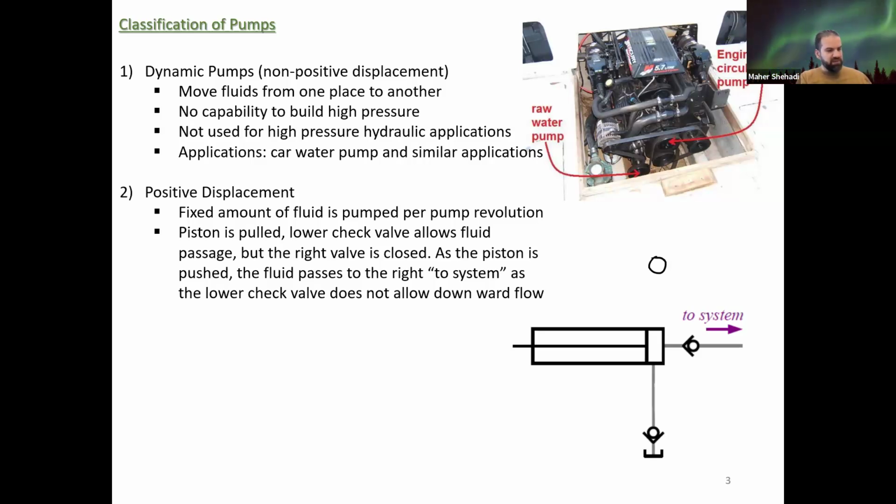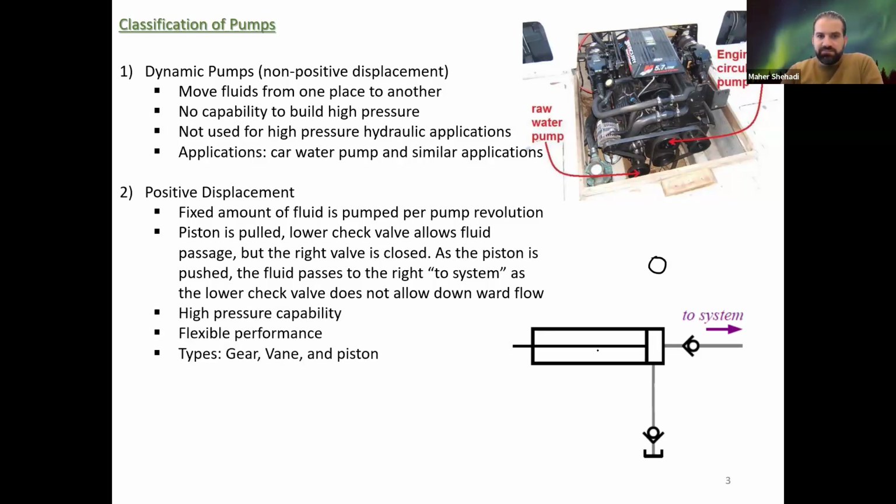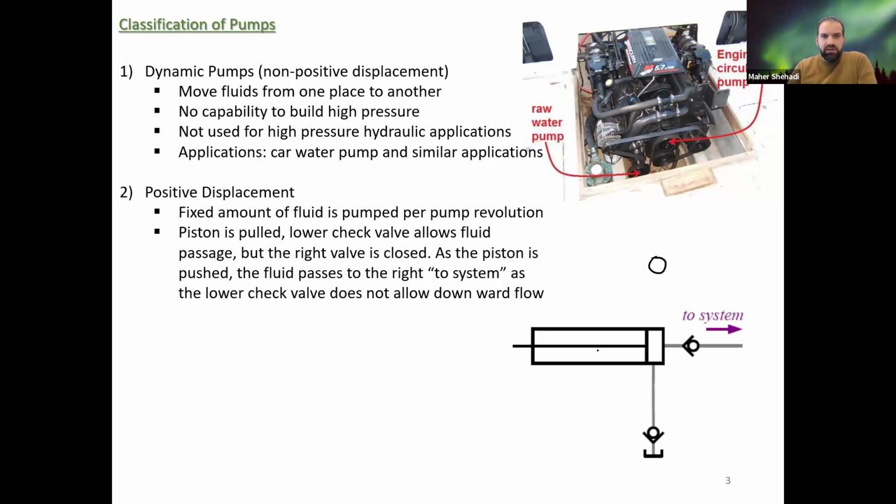In the coming slides, we'll see how the volume actually changes from large volumes at the inlet to smaller ones. So once it's smaller, it's going to pressurize the fluid so it exits with a higher pressure. An example is this hand pump. We see those in parks, for example.